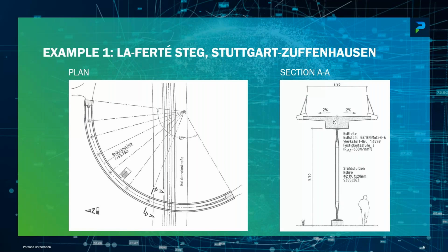But the interesting part is the column is taking only the vertical load, nothing else, no lateral load or torsion. And in order to facilitate the lateral movement, this column has a special shape, with two bottlenecks on the top and the bottom, so that it can act as a pendulum, but there are no bearings. These steel cast members are shaped like a wheat beer glass. We call them in Germany wheat beer glasses. And they have an extremely long bottleneck in order to allow rotations that are more or less elastic during the temperature movement.